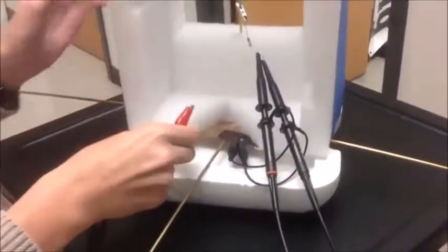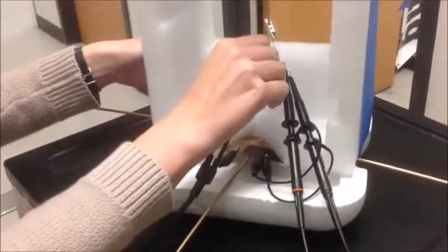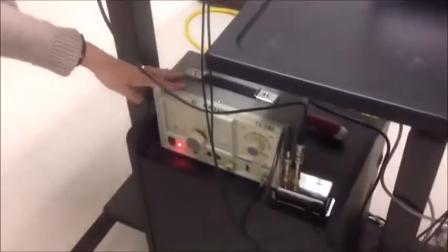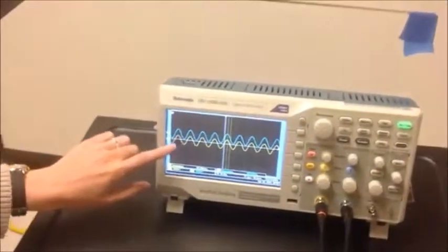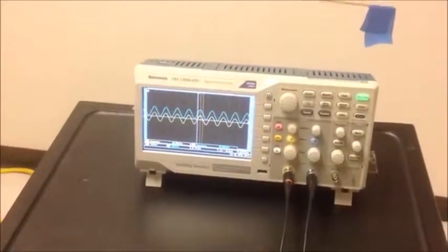Lastly, you're going to take the function generator and we're going to hook it up also to the ground and the 1 kilo ohm resistor. From there, you can adjust your function generator and your oscilloscope to give you a good resonant frequency around 83 to like 90